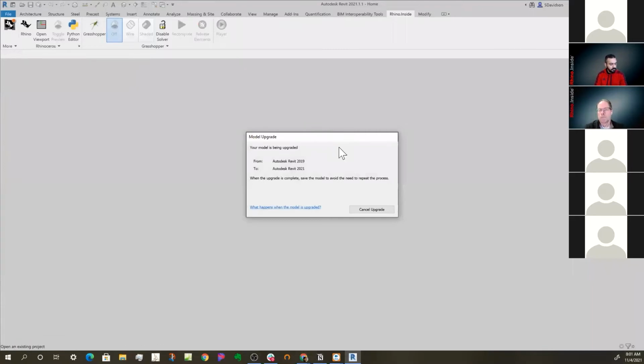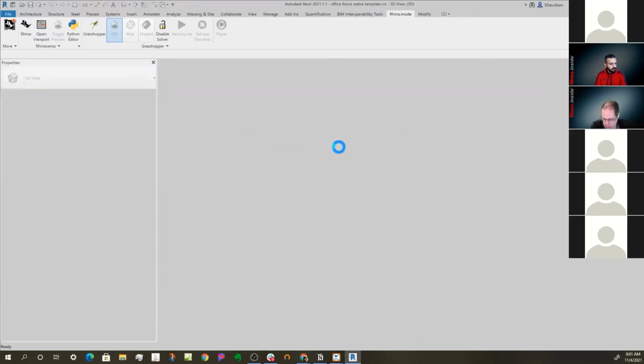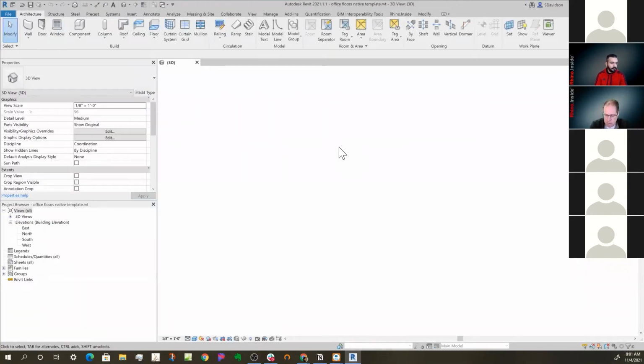So it's important to understand, and I saw this in the survey too, if you create a family in Revit that has sweeps and extrusions, and it has objects that have parameters, you're not going to overwrite that in Rhino. You don't want to. But what you can do is set all those parameters with Grasshopper later in the process. That's what you want to do, set those values either on the type or the instance itself.